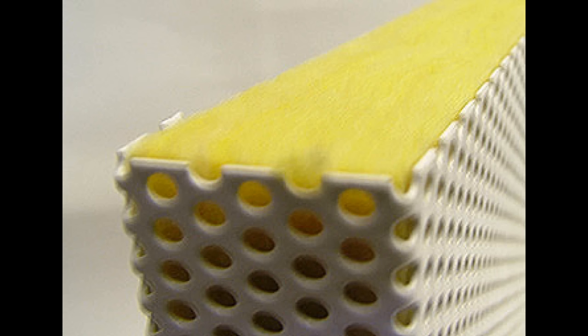Perforated metal panels, 2 inches thick. I always used 4-inch thick panels. Often use them for exterior applications. With a barrier on one side normally, and then that 2-inch, 4-inch area is filled with acoustic fiberglass or mineral wool generally. There are other products you can use also. The perf pattern is important so that it's acoustically invisible to sound, so that the sound gets into the absorptive materials. And right off the top of my head, I don't remember the proper size and dimensions of those.